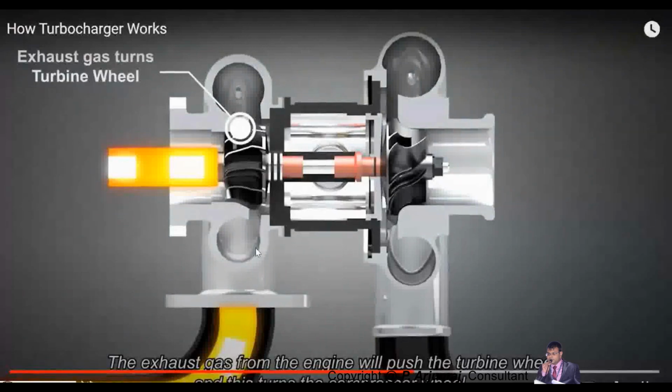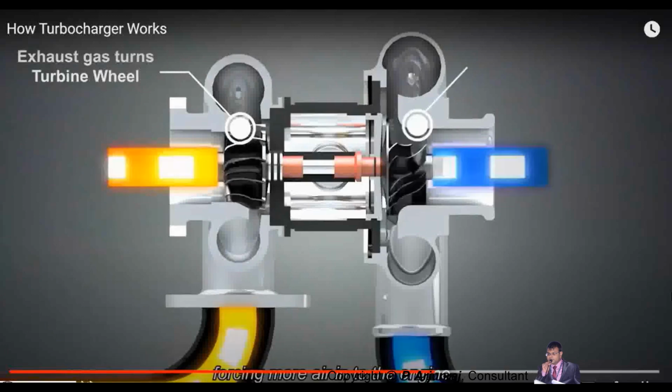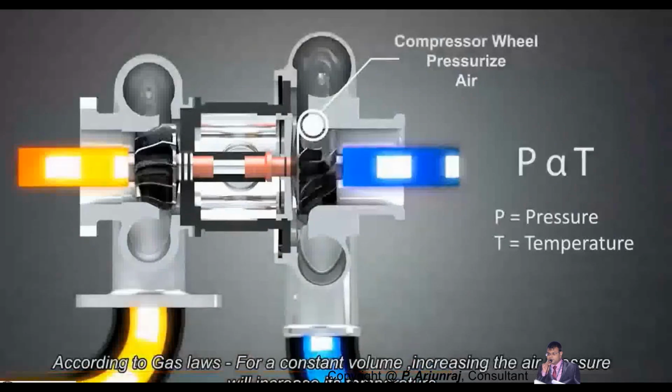For which we need to use the intercooler, which will reduce the temperature and also increase the charge density. I gave the principle of the charge density. When you increase charge density, you're going to increase the volumetric efficiency also. This is the reason why we go for an intercooler. Because when the pressure is getting increased, your temperature is also getting increased.